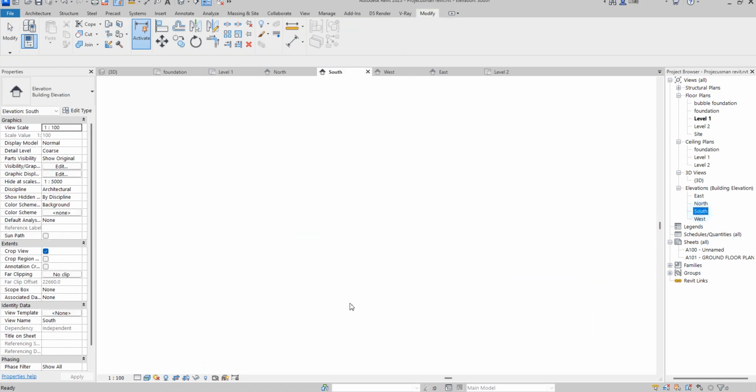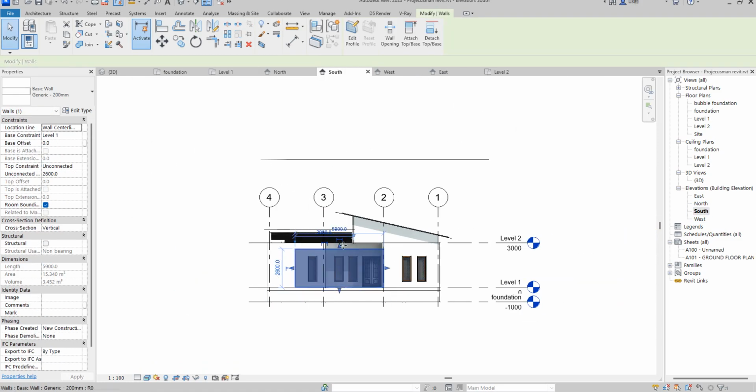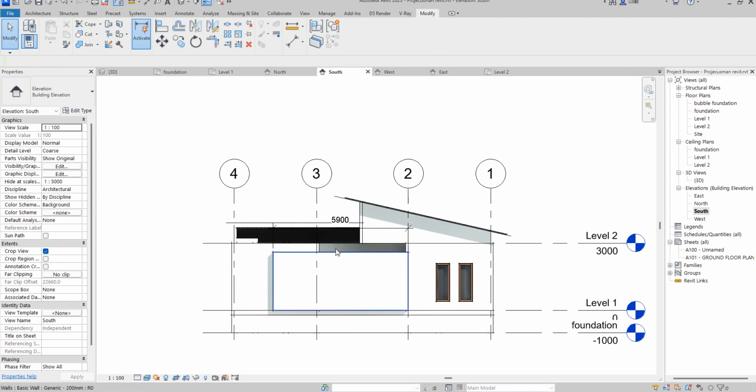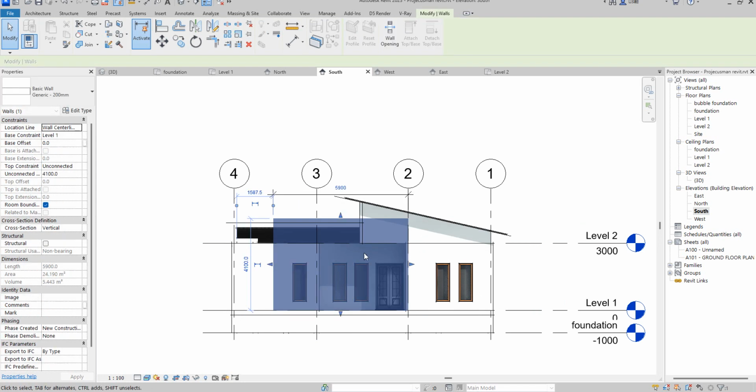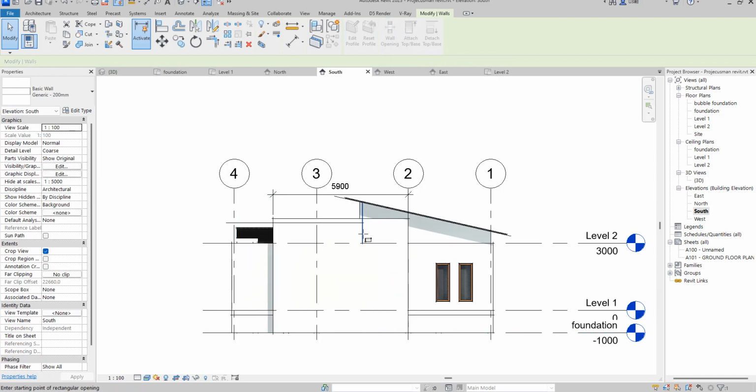So I'm going to go to start elevation now, then we'll drag it up as far as I want it to be. So it's going to be like that. Here now I can edit whatever I want to edit. You can drag it down as well, then here you just need to edit. You can use opening wall to do the editing or whatever pleases you.